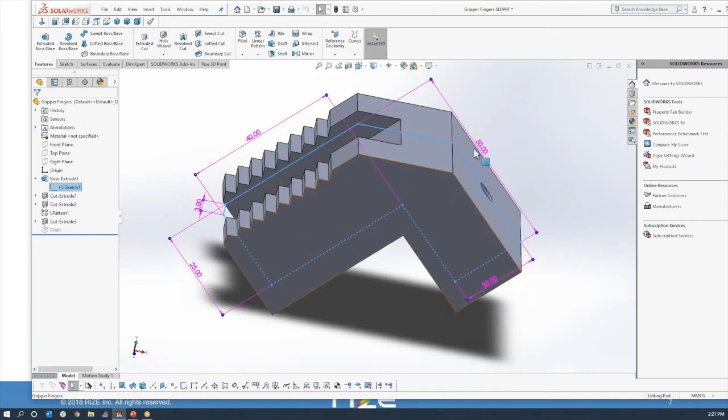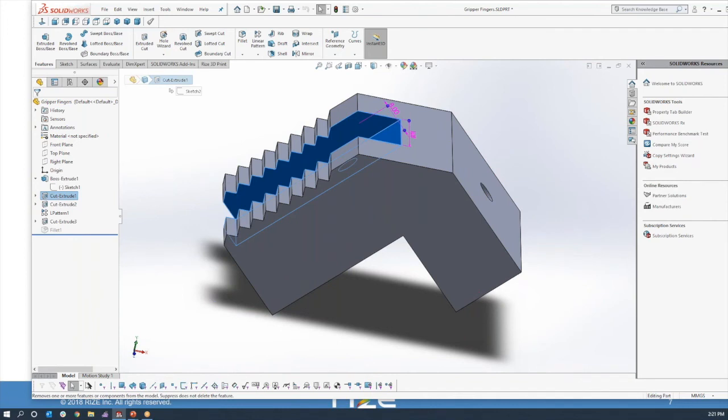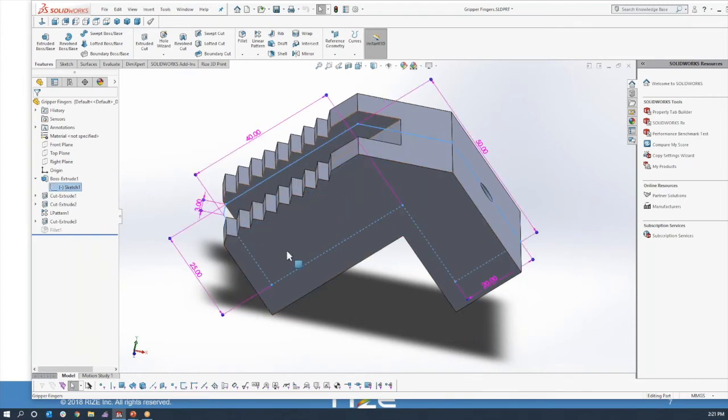Each of these lines has some dimension applied and presumably some tolerance associated with it. This has additional ones. So essentially what you would do to use this iterative remodeling approach would be, after the part has been produced, you then measure all of the dimensions that you care about being accurate and record the variation of each of those from the intended dimension.